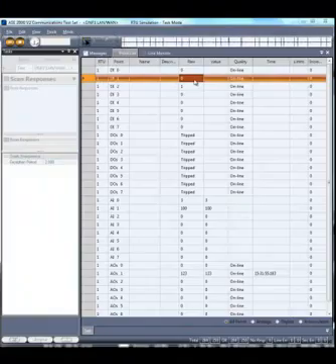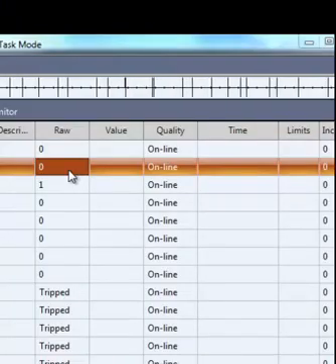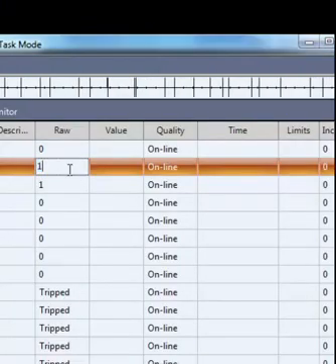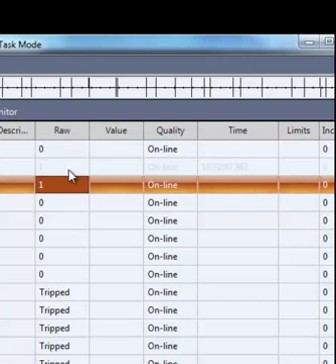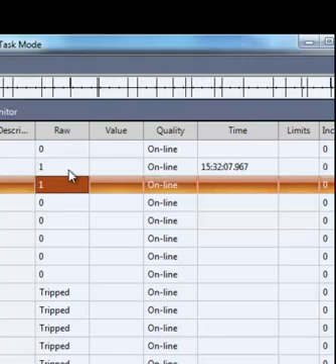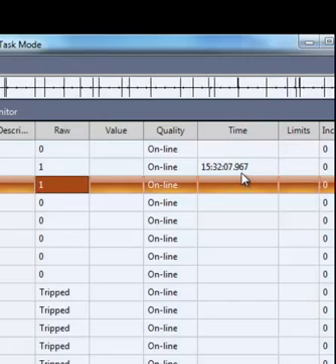To send a new value, simply enter it in the raw field. The line will change to dim as shown, indicating that a new value has been entered but not yet sent to the master. Once sent, the view changes to normal video. Each manual entry generates a time-tagged events message, which is transmitted to the extent supported by the underlying protocol.